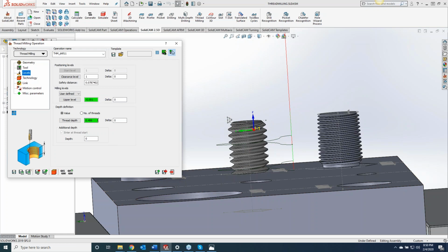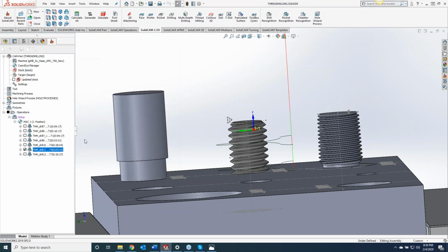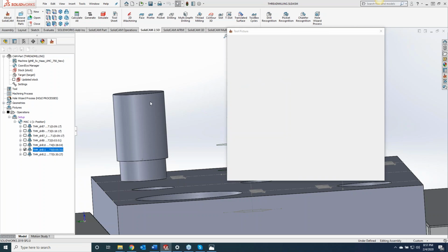So, yep, great point. And I also chose 4 teeth very specifically because anytime you have 3 teeth or less, it's going to do the entire helix. So if you do want it to cut everything, even if your tool has more teeth than what you specify, if you set that to 3 teeth or less, you will get the entire helical profile. As soon as you go above 4, then we start breaking it up and optimizing that tool path.